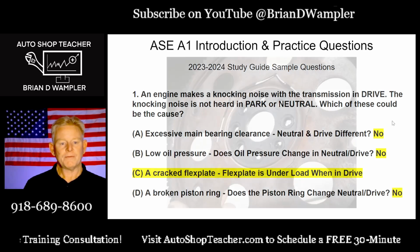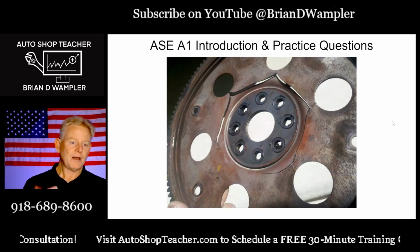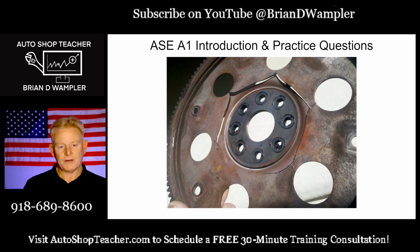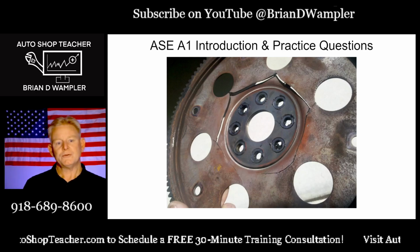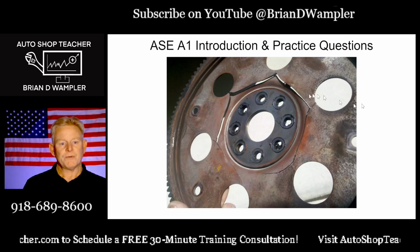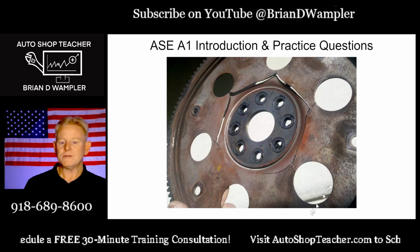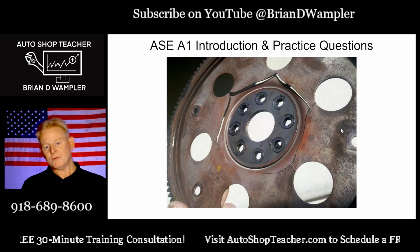So let's talk about flex plate real quick. Flex plate is on the rear end of the crankshaft between the engine and the transmission. We use a flex plate when we have an automatic transmission. It's much thinner, but it still has the ring gear that's used for engaging the starter motor. It's much thinner and lighter, and it just provides a way to attach here in the center to the crankshaft, the output of the engine, and then you can see these bolts around the outside where the bolts connect to the torque converter.